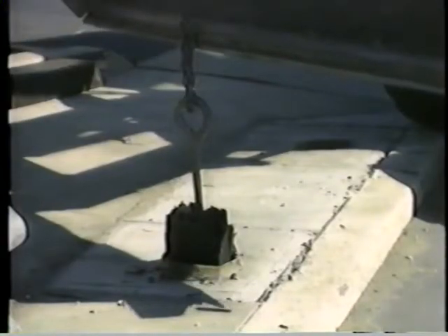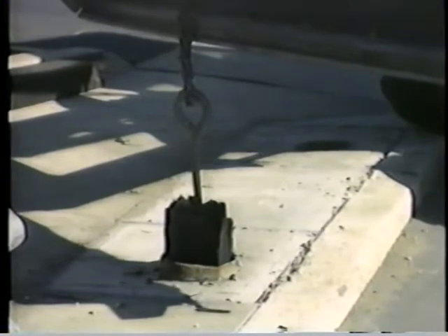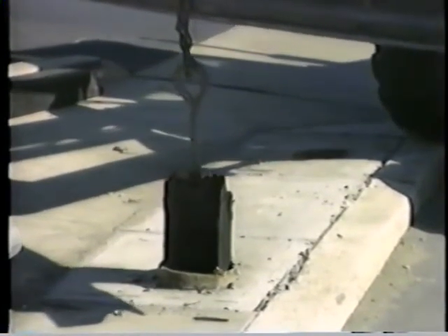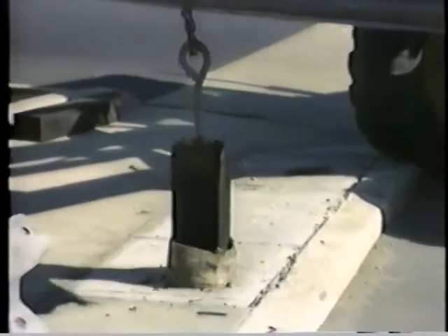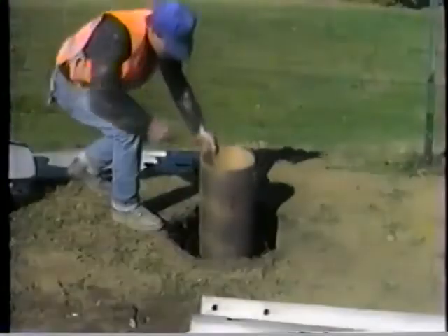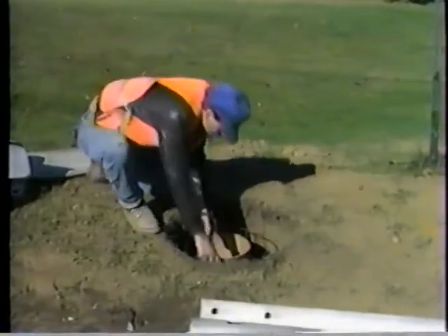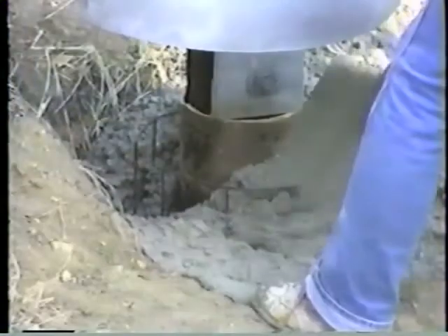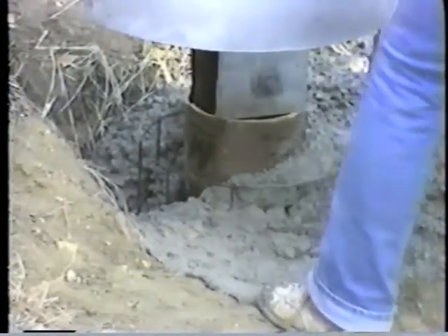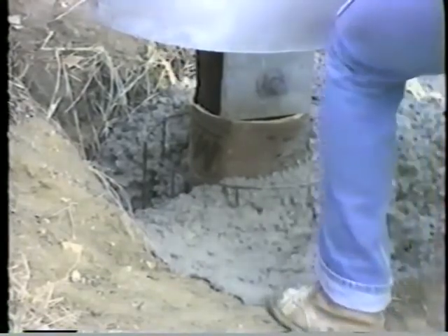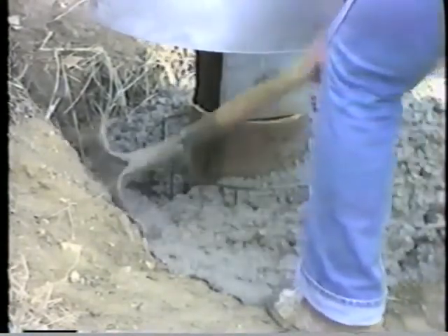Removal of broken stubs has created some problems, with several solutions being worked out. A styrofoam sleeve and a steel sleeve with soil plates are 2 different concepts available. Another solution has been to place a heavy pressed paper tube around the post when it's installed. The footing is poured around the outside of the tube. Now, care must be taken to ensure that no concrete is placed between the tube and the post.